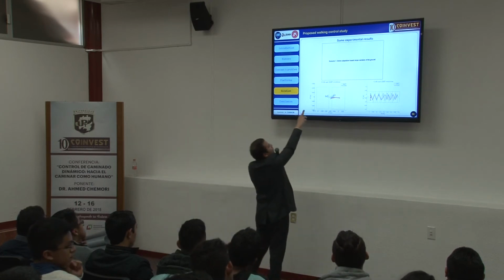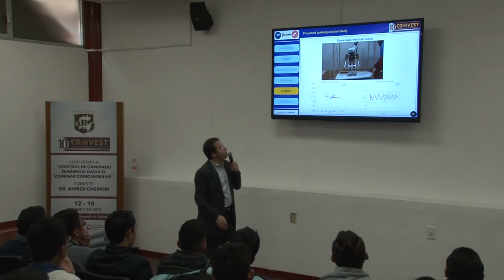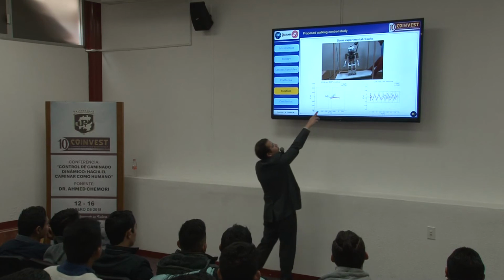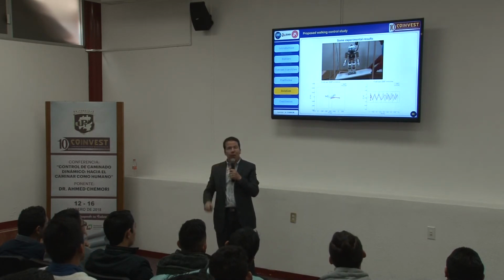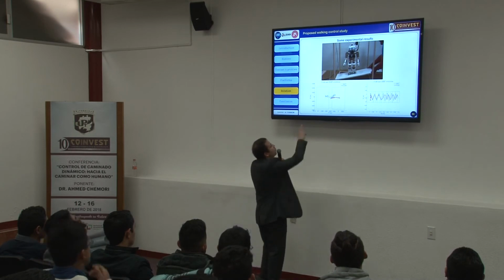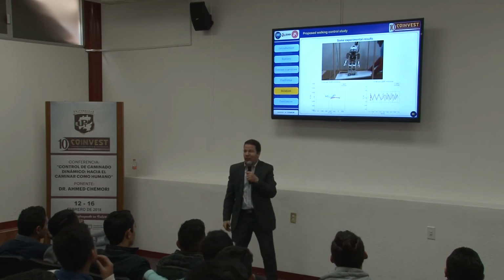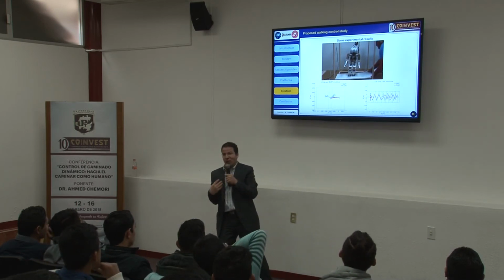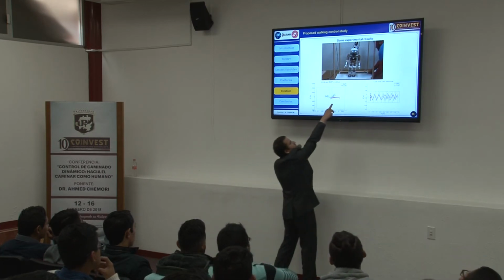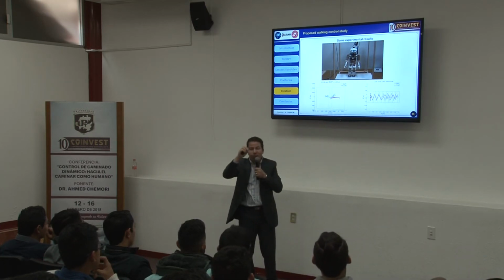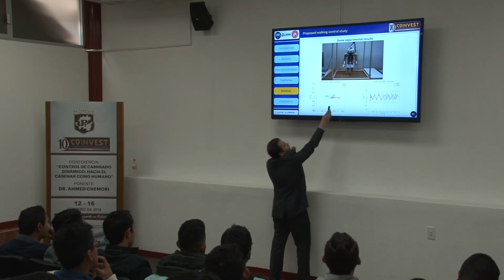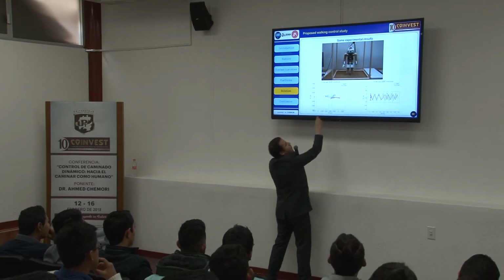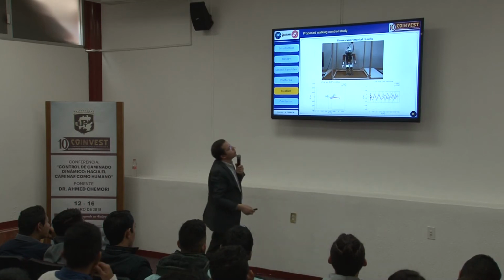We have tried also on the Hope 3 humanoid robot for different scenarios. First of all, we try to modify the slope of the floor, as you can see, and we don't ask anything of the robot. We just apply the controller, and look, the robot is automatically modifying its posture to compensate for this disturbance. And the idea is to keep the ZMP inside. Look, the ZMP is in blue, and the center of mass is in red. So the ZMP is inside the polygon of support.